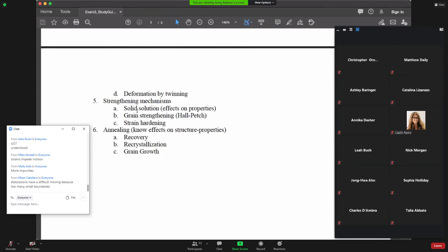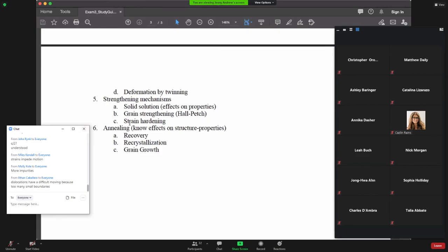And then as you start getting more and more dislocations in your system through this dislocation pileup, it's going to be even harder for them to move or even to generate them because you already have such high strain energy, so many dislocations in your system. And that kind of leads into strain hardening, where the more dislocations you have, the less likely they are to move because they don't want to come near one another. Good?